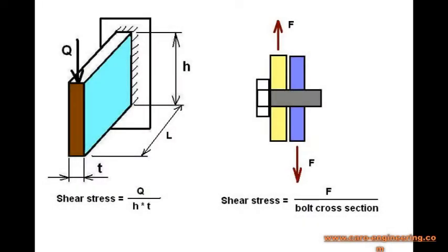Normal stress is not the only kind. There are more, such as shear stress. You will be familiar with one of the applications. Every time you use scissors, you exceed the shear strength of the material you are cutting. A more airplane-related example is a beam, such as a spar that is loaded with wing shear distribution we calculated during the loads analysis. The simplest form of shear stress is calculated by dividing the shear force by the cross-section